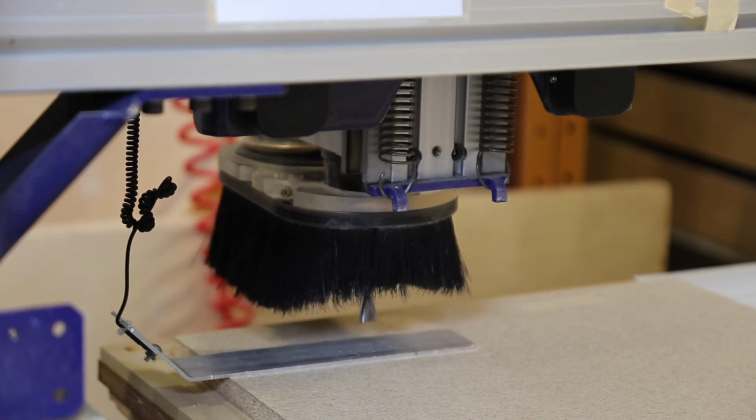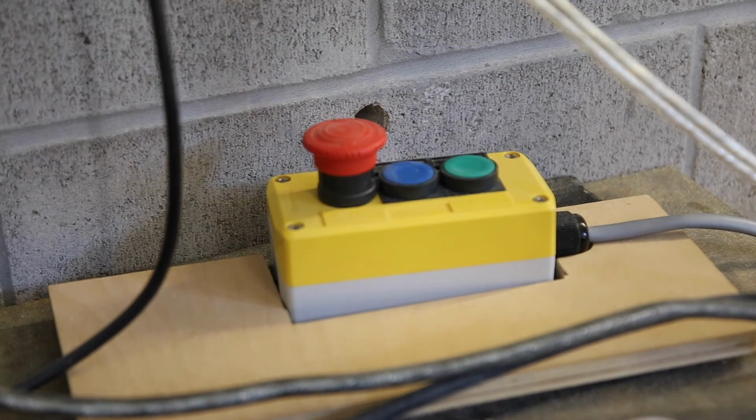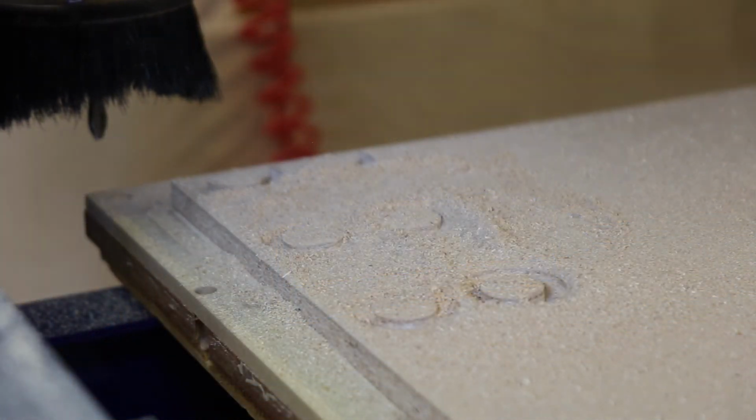If you use the red emergency stop, it will lock in the off position. Check this when you restart the machine and turn it clockwise to unlock the stop function. Otherwise, the machine will not run. If the machine is left in this condition, it will potentially confuse the next person who uses it.